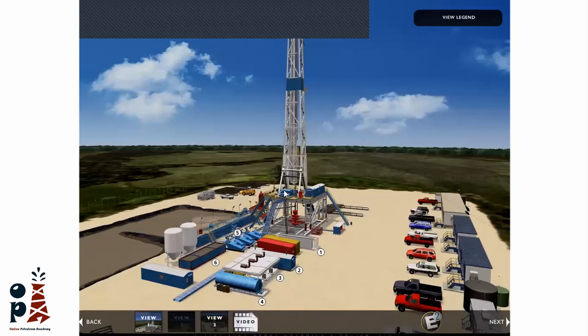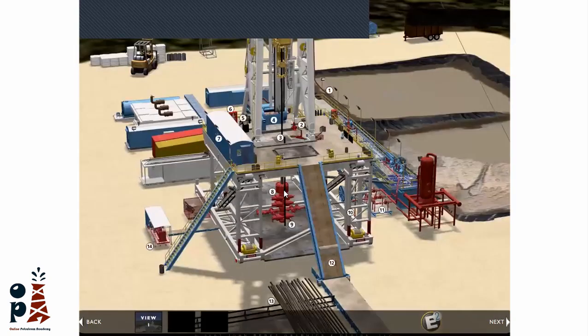What is the importance of the mouse hole? The mouse hole is a small pipe extended from the rig floor to close to the cellar area. We can use it to put the joints that are going to make a connection, or any small pup joints. So it is just a reserve for the joints to be used next on the top drive. Also, you will find here the catwalk. On the catwalk we put the pipes, and they go to the V-door, to go to the rig floor through this inclined V-door.